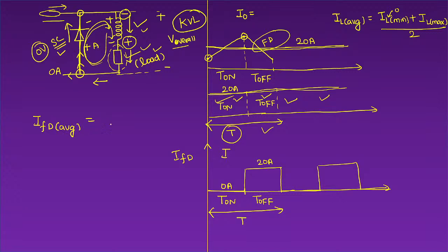See, it can be estimated in terms of the output current. Basically, this current is the output current, and this output current is flowing through the diode. How will you write down this formula? Let me tell you. Simply, average means area by time period. That is very simple. T denotes the overall time period, the fundamental time period. But for the on time, the height is 0. Current will be 0. Width is only T on. So 0 ampere current into T on. It is rectangular only, right? Area, how will you calculate?